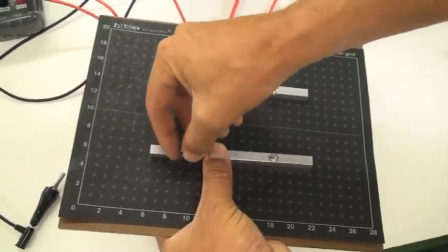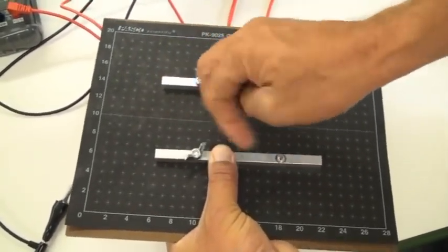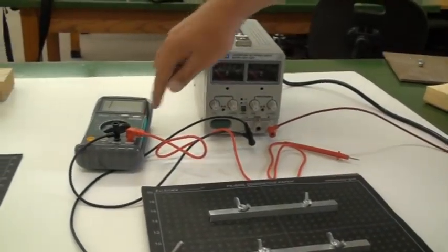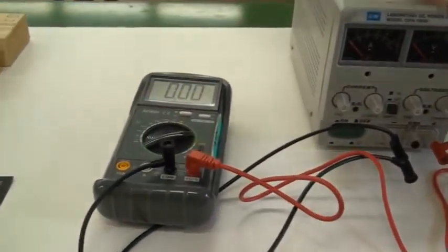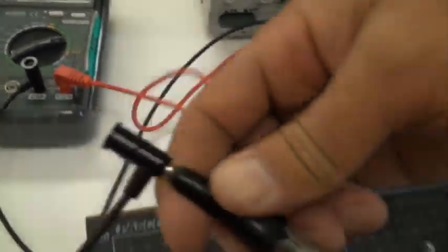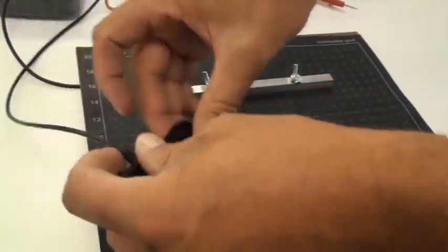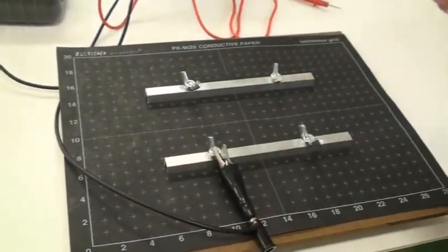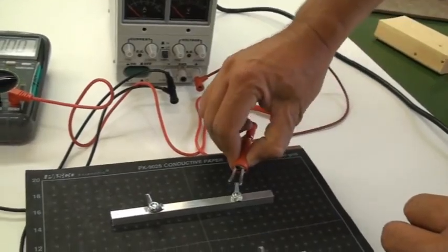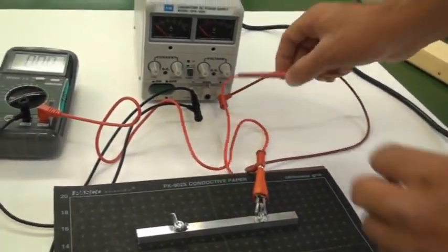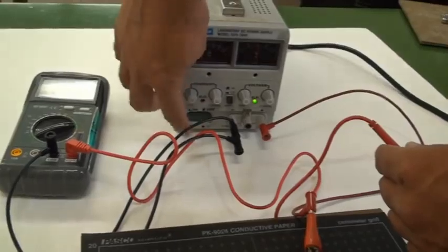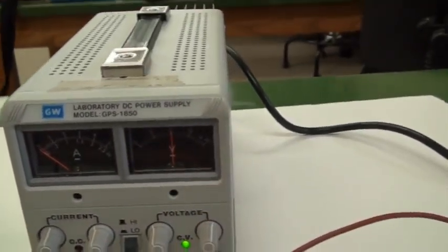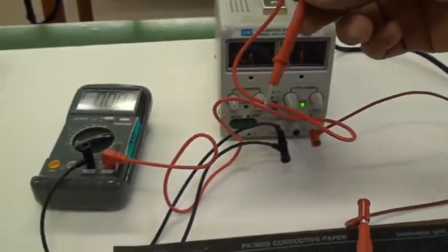As you'll see, we neglected to screw one of the nuts tight enough when we were constructing ours, and this led to later problems. With our 2 conducting strips screwed firmly in place, we connect the common input of the voltmeter to one of the strips using the alligator clip. Then connect the high voltage output of the voltage source to the other strip. Turn on the voltage source and adjust the output to approximately 10 volts using the coarse adjustment knob.